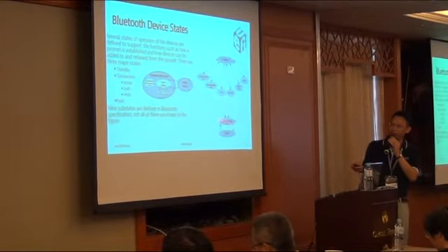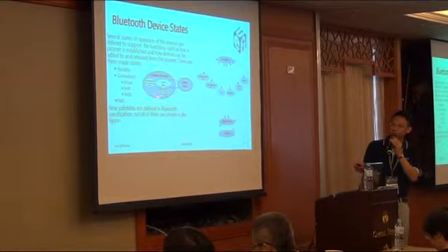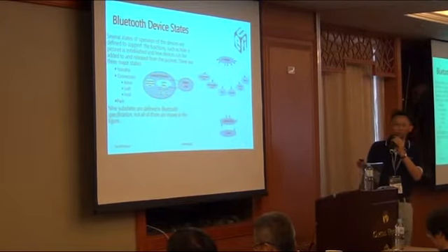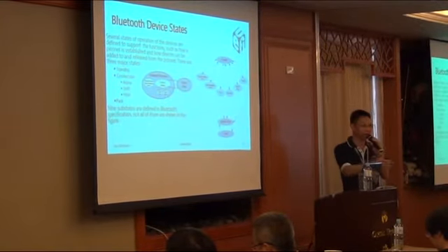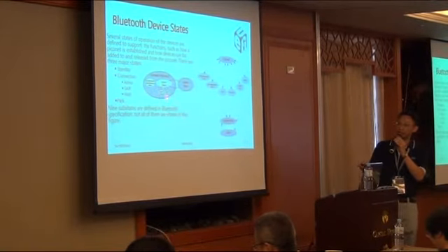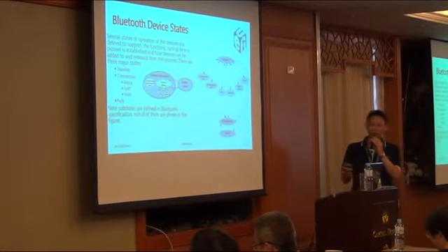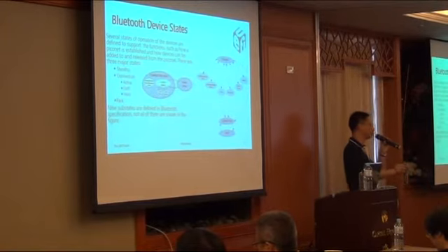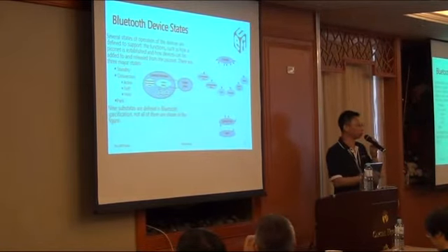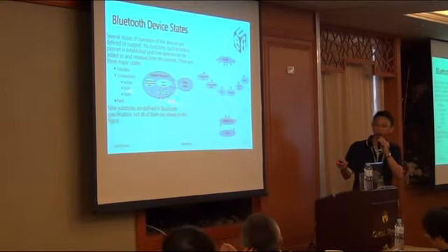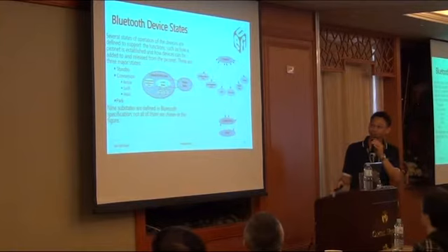And when a device is already connected, there are also different states represented here: active state, hold state, sleep state, and the park state. For park, we already explained it. For an unused device that you want to make idle, you can put it in the park state. And for sleep and hold, compared to the active state, they will occupy fewer resources. So for the master, if you have a resource management request, like you want to reserve some bandwidth for a special device, you may move some devices to hold or sleep.